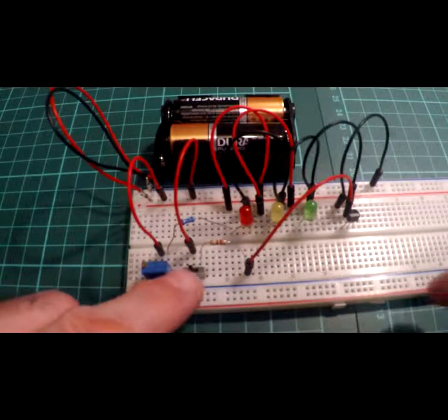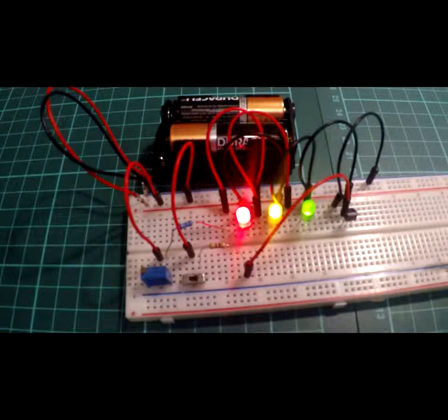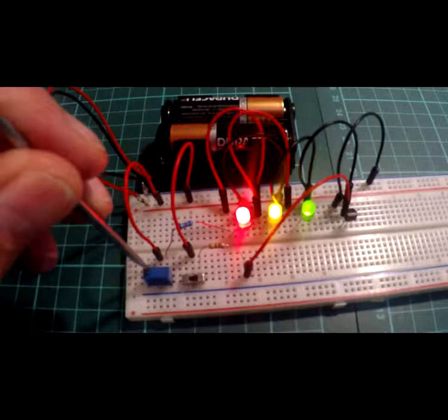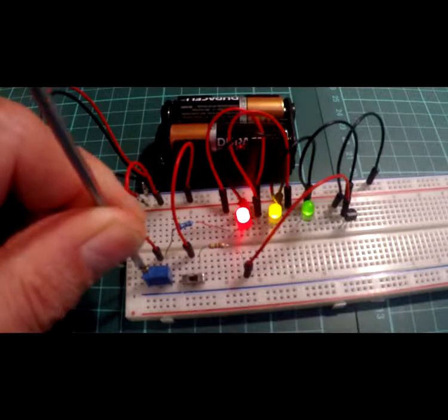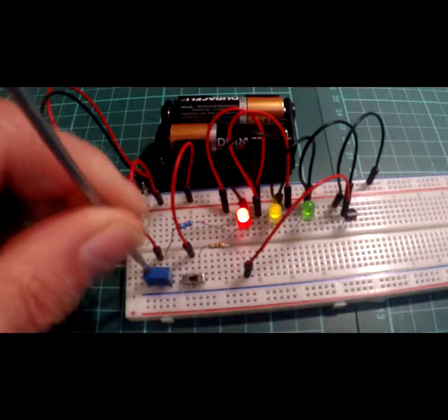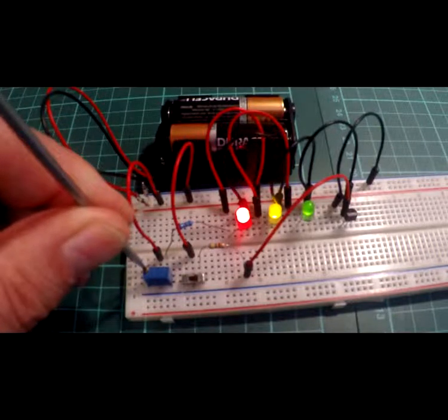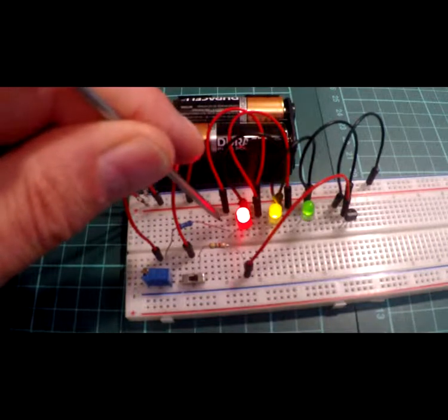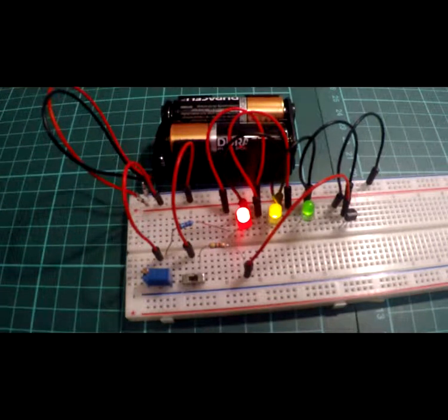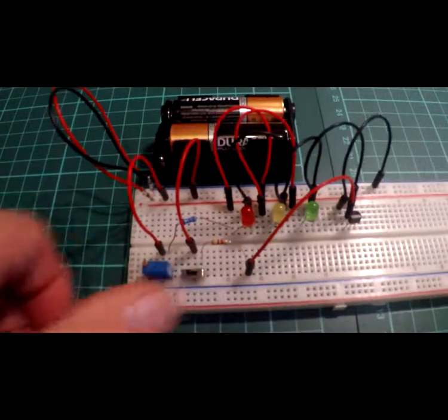Now if I turn that on, what I'm actually doing is turning on the power to the base of that transistor, which is its middle pin. Now if I turn the trimmer one way or the other, it should dim the LEDs. Now that dimming is dimming the power to the LEDs from this end, but the transistor is turned on via the switch here, and then the transistor switches on the LEDs, and the trimmer is just there to dim them.